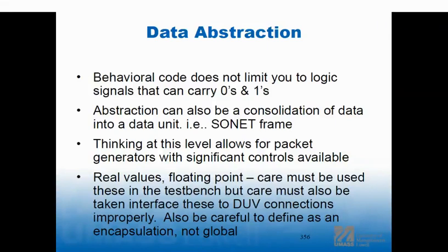And then I would look at the coverage. If I went and looked at the coverage, I might see that a signal in there called forward, which forwards data if there was a data hazard, was uncovered.